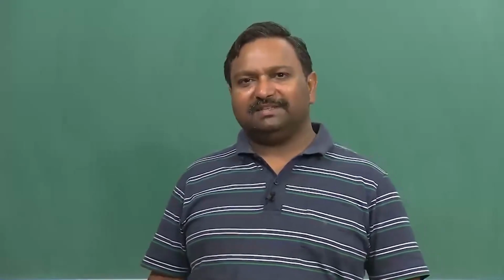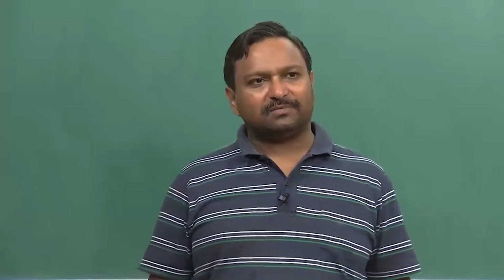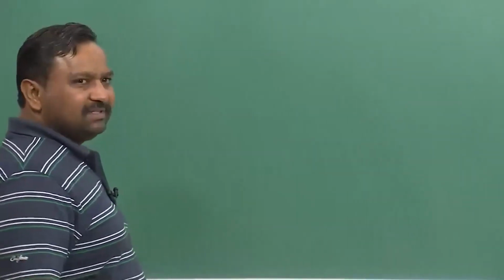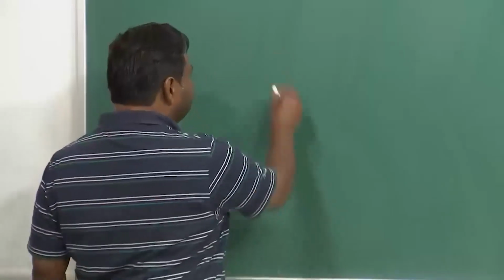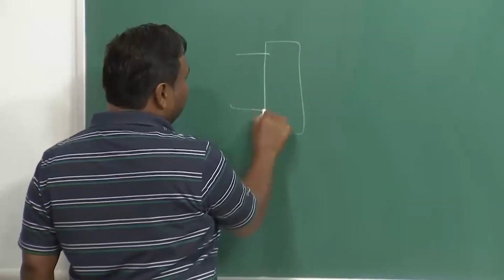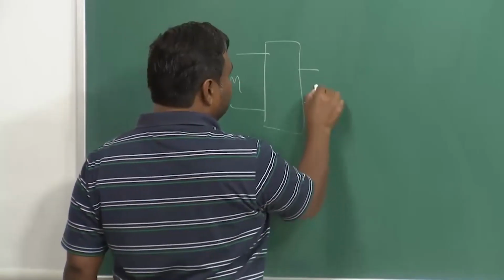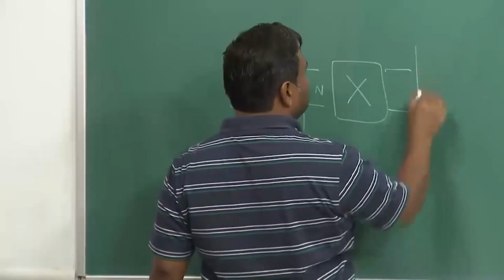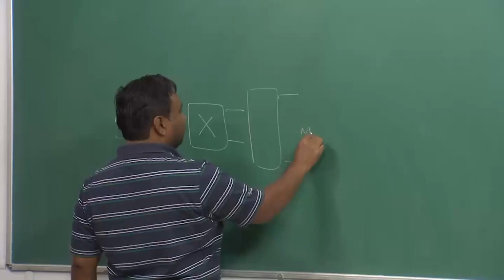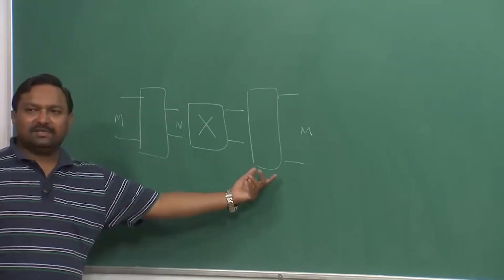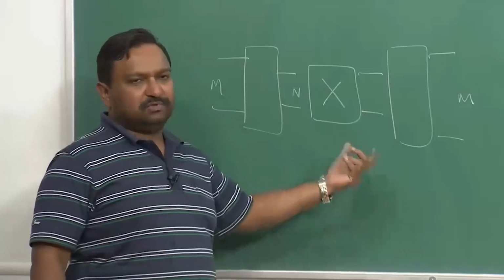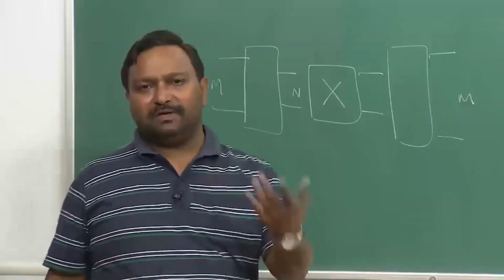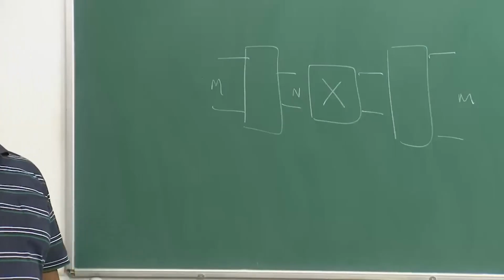In fact, we do two things. We either build only blocking switches and use them to reduce the cost, because a certain amount of blocking is acceptable, or we create a strictly non-blocking switch and then introduce blocking by using concentrator units. That means I have a special kind of switch where the number of inputs is large and the number of outputs is small, use a strictly non-blocking switch and connect it to the large one. So I have introduced blocking; this is known as a concentrator unit, and that is a switch. This configuration has also been used in a lot of telecom switch implementations.